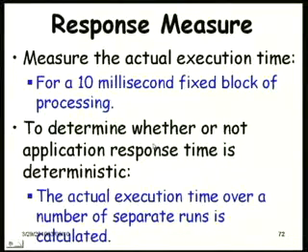Here you are trying to determine whether the time that it takes to execute is deterministic or not. Remember that the task you are running here is a real-time priority task, and a real-time priority task should not take different times at different instances of run.